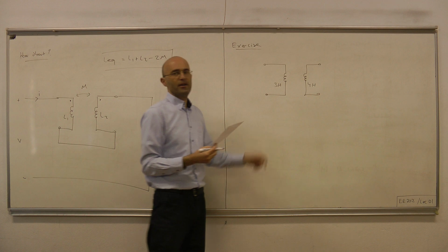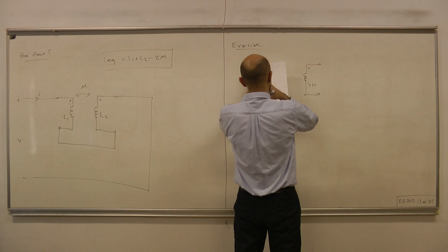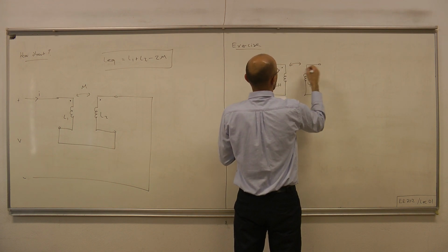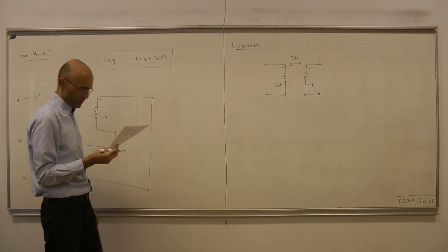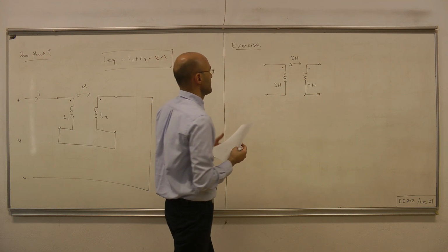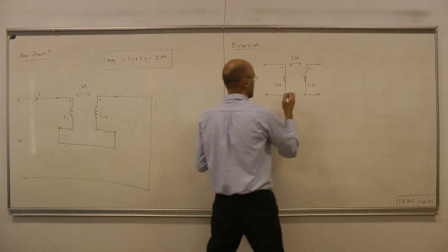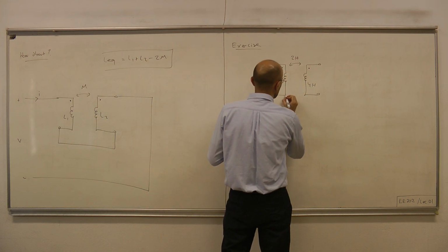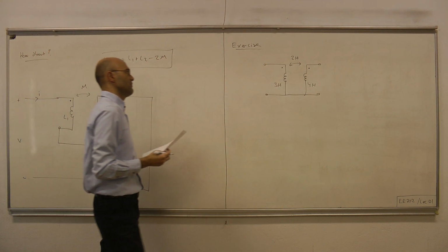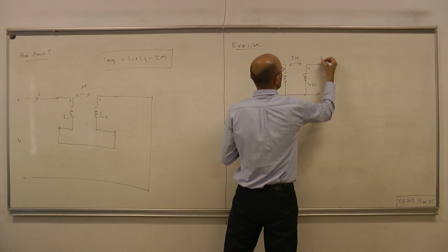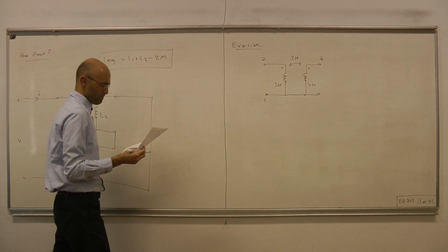These are 300 and 400 self-inductances, and the mutual inductance with dots placed as such is 2 Henry. And then, from this device, you obtain a 3-terminal device. Right now it has 4 terminals, and by shorting these 2 terminals, you obtain a 3-terminal device. Let's call the nodes A, B, and C. This is also C, because they're shorted.